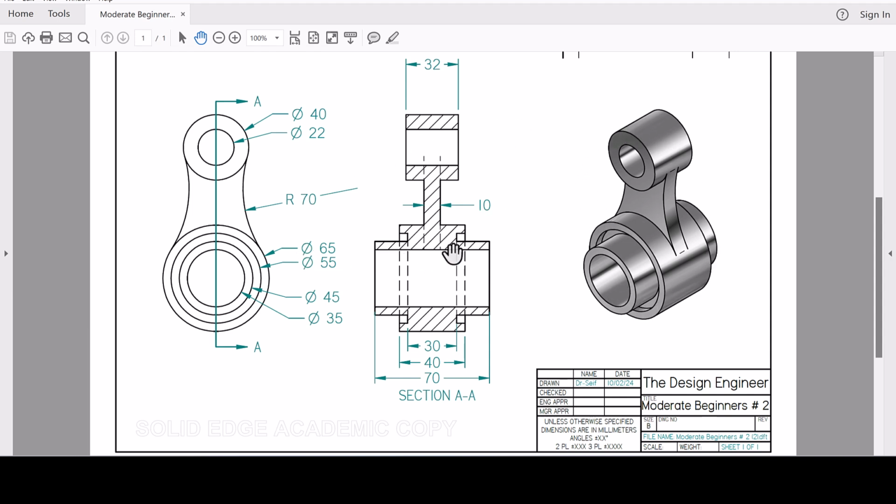In this part, we're going to use synchronous technology and the extrusion select to create this part, but also at the same time, we will learn how to do different sketches, concentric circles and tangent circles and so on. And at the same time, I will show you how to get a section so you can reveal what's inside here, the cross-section area. Sectioning is just a very easy process. I will show you how to do it in this video and so on.